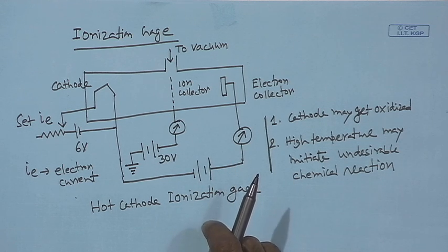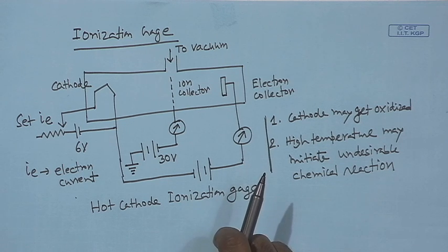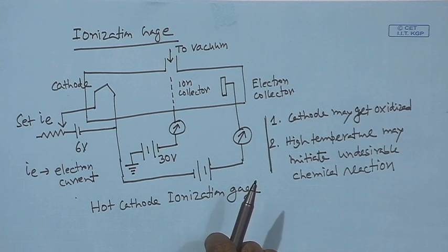Instead, a high electric field between cathode and anode is used to draw out electrons. Then a high magnetic field of about 1500 Gauss is imposed, which causes the electrons to move towards the anode in a spiral way.